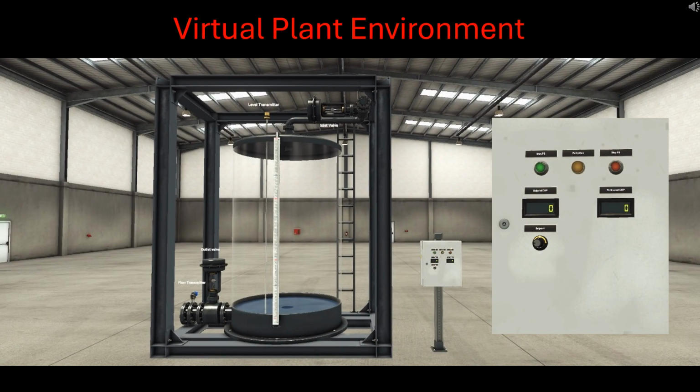The generated virtual plant in this scenario mimics a single tank level control system with an operator control panel. Important to highlight that the intelligence to run the system will be externally sourced by the Modbus client. Respective GUI elements, like the valve, only respond to variable changes within the I/O Modbus registry, hosted by the server.